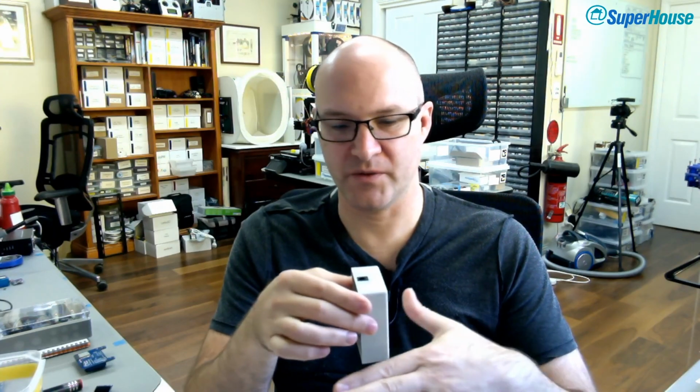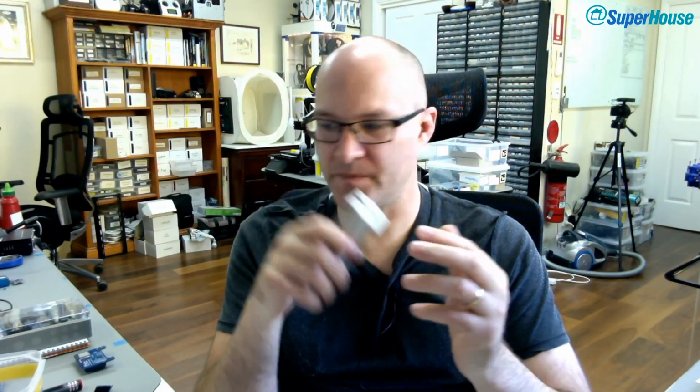The better way to do that is with CNC machining. What you could do is make a fixture. I've got a CNC machine over in the corner, that corner, which you will see in the lab tour video. And the more scalable way to do this, if I was doing more of these, is I would make some kind of a fixture that allows me to put the box down in a very repeatable place. So I would probably make something that has an L shape in it that this fits into, and that's where it registers against the corner. So you've got a known starting point every time, and then clamp it from the opposite corner and use a CNC machine to cut the hole out of it. The setup involved in doing that was more than the time involved in just manually cutting some of these holes. So if I was doing a bunch of them, I would CNC them.